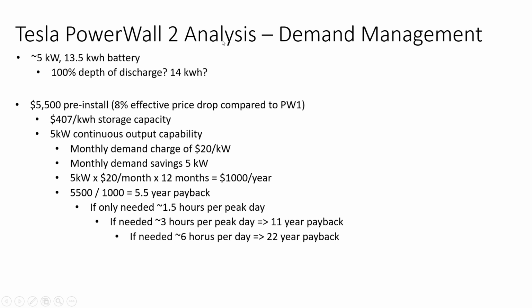And for those reasons, the real economic solar batteries are either off-grid where you have to use them, or demand management where you can go after these demand charges. But for most energy-only rate structures, the battery is not really there to save the customer any money.